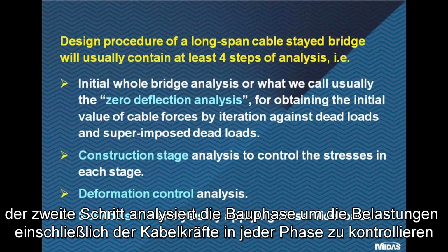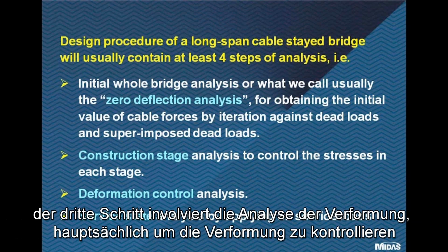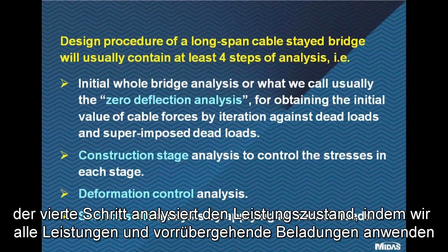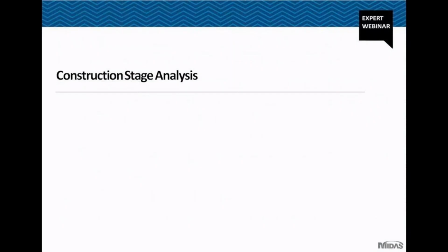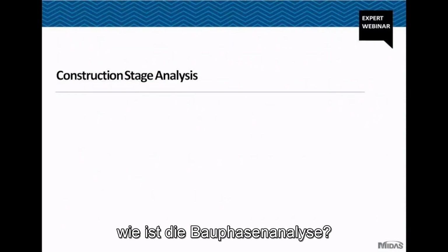The second step will analyze the construction stage in order to control the stresses, including the cable forces in each stage. The third step is to analyze the deformation, mainly for the deflection control. In the fourth step, we analyze the service state by applying all service and transient loads. How is the construction stage analysis?